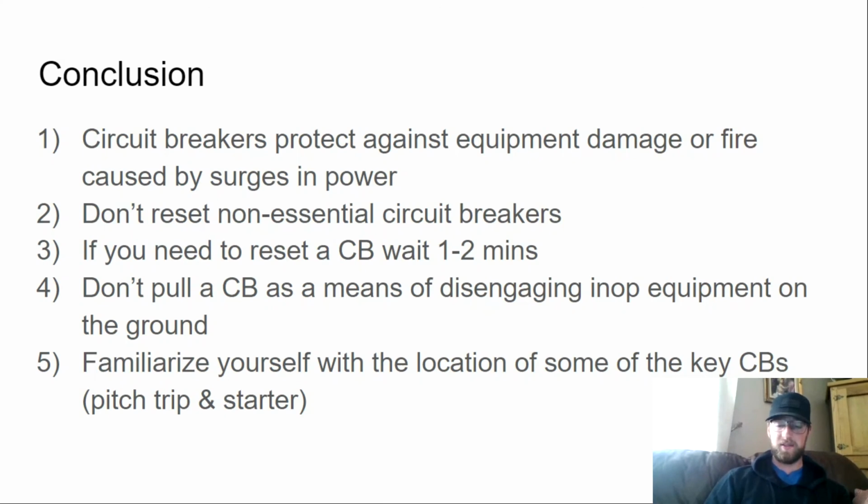Don't reset non-essential circuit breakers. 2. If you need to reset a circuit breaker, only do it once and only after waiting at least 1 to 2 minutes for the internal components to cool down. Number 3, don't pull a circuit breaker as a means of disengaging inoperative equipment prior to a flight. A mechanic is needed for that. And number 4, next time you're in the Seminole, take a second and try to locate some of those circuit breakers I talked about, some of the key ones, some of the ones you might need in a pinch, like the electric trim circuit breaker and the starter circuit breaker.